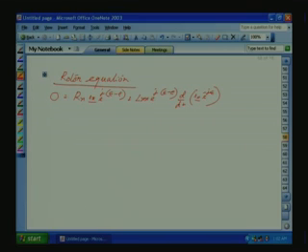See, the rotor equation is originally defined with rotor axis. By multiplying by e raised to minus j epsilon, we are trying to bring it to the stator axis. But already we have multiplied e raised to j (epsilon minus rho).